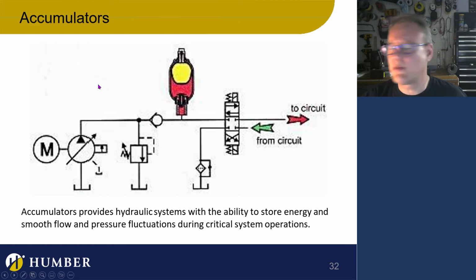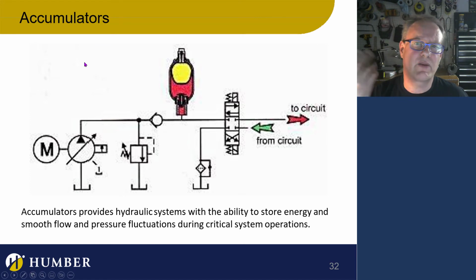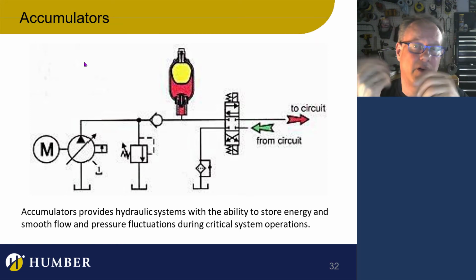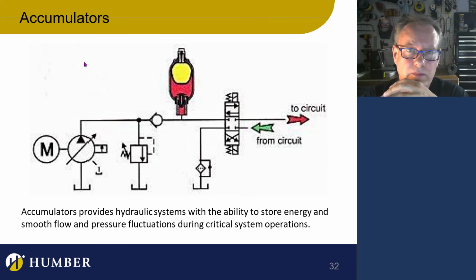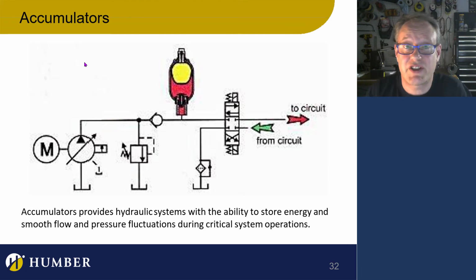I want to talk about accumulators, and then I'm going to let you go. So just bear with me here with the accumulators. Accumulators are really cool things. We talked about them in pneumatics to some degree, and they're used for the same reasons in hydraulics, although they work a little bit differently. They're mechanical. If you think about it, an accumulator for air is pretty easy. I even showed you an accumulator for air when I was doing my pneumatics lecture. I got one in the drawer over there. All it is is just a tank, right? It's just an air tank.